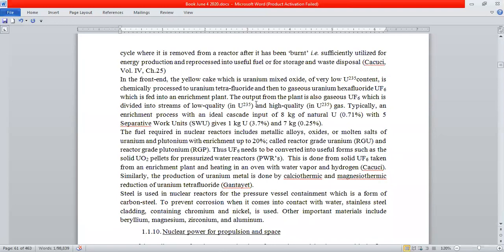it would have a turbine, and then it would have recirculation of the cooled steam, again becoming water, condensing to water, and then you would have 1 or 2 cycles. You would have direct cycle or indirect cycle, and you would basically transfer the heat out of the core into the steam turbine, into the secondary side. So there's a primary side and a secondary side.